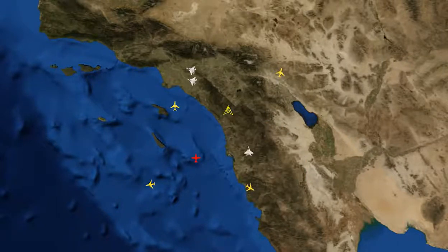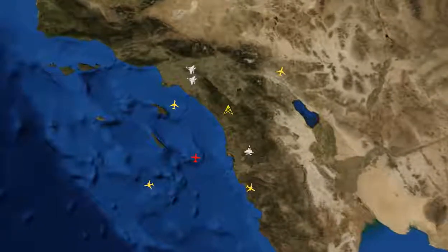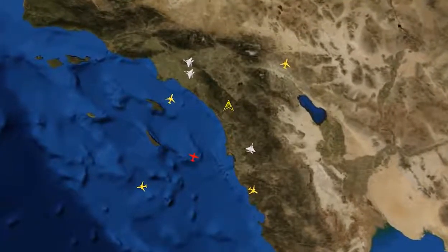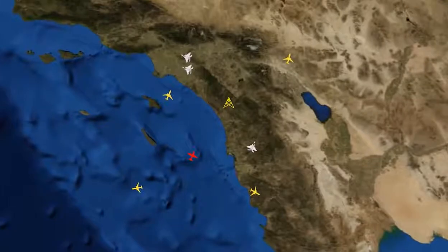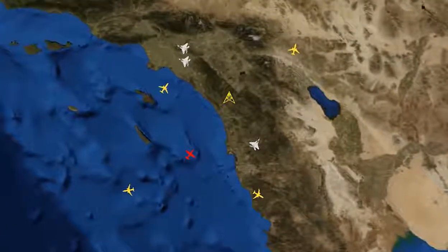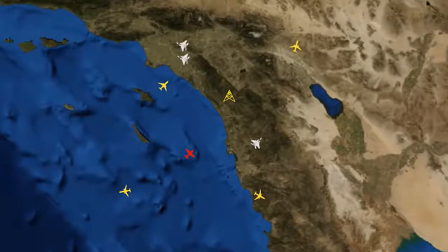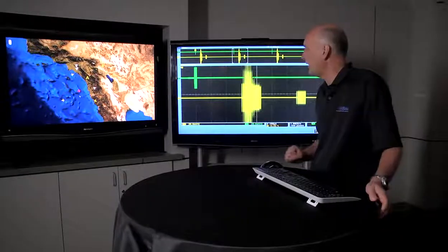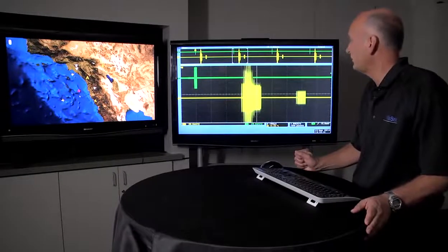In this scenario, we're still transmitting with an omni antenna, so all platforms will respond no matter what the pointing angle of the system under test. We have 4 commercial planes. They're capable of all modes. We have 3 military planes that are not Mode S capable, and we have a ground site that is also capable of all modes. You can see as we're generating interrogations, we've got a garbled effect as platforms are over the top of each other.